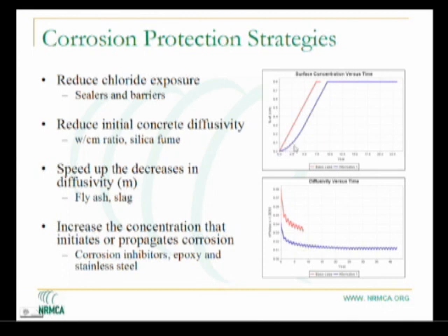you can reduce the actual level of chlorides that are exposed directly to the concrete over time. It's as if you put a cap on a tooth and you've been able to reduce the actual level of surface layer exposure, and do this in a way so that the actual amount of chlorides that are on the concrete are reduced. And you do that through the sealers and barriers.